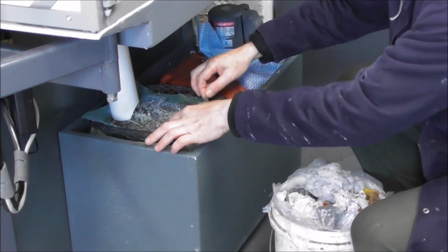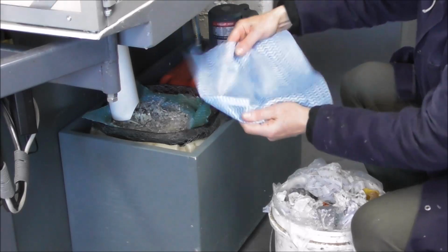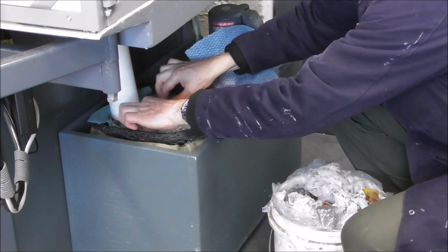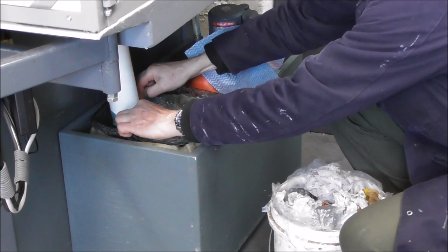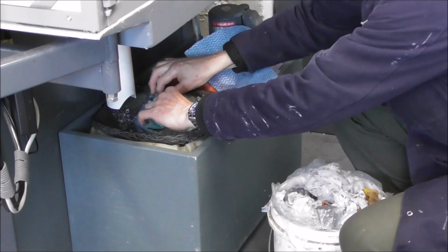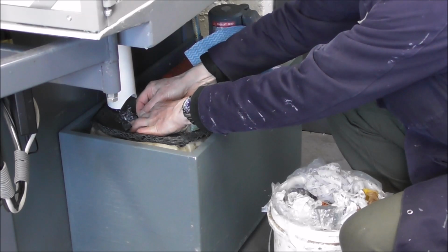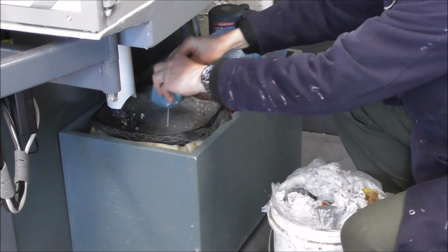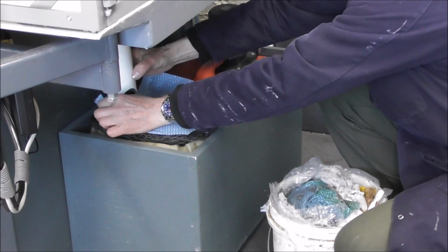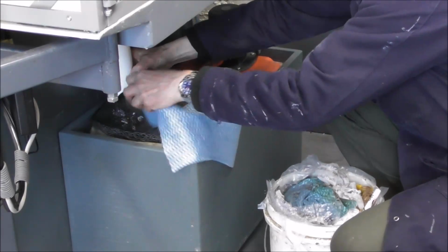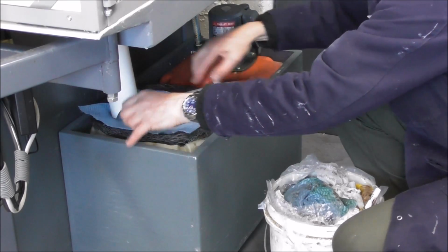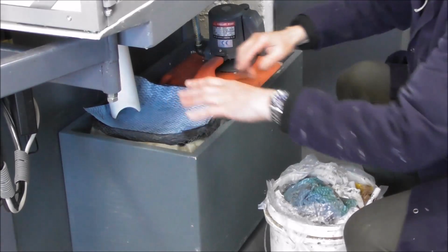You've probably already thought of this one, but in case you haven't, it's a good idea to have a piece of clean synthetic cloth and just put it on top of a gauze filter. I'm going to make a mess of this. It's all going to go pear-shaped, and then just dump that, so that what you're doing is actually filtering the cutting oil as it's coming through each time and helping to extend the life and the condition of the cutting oil.